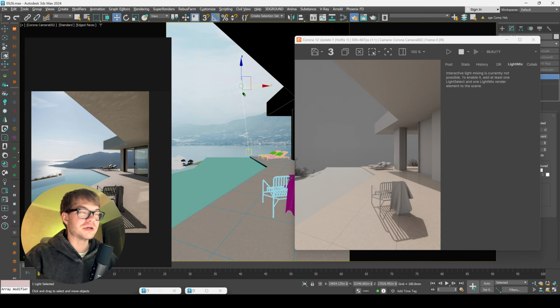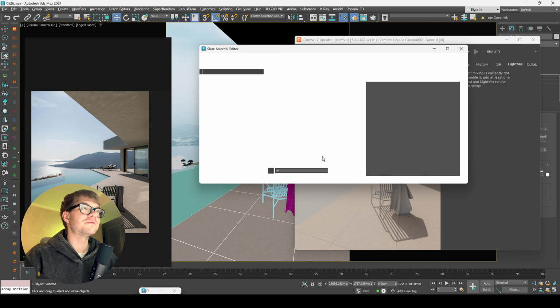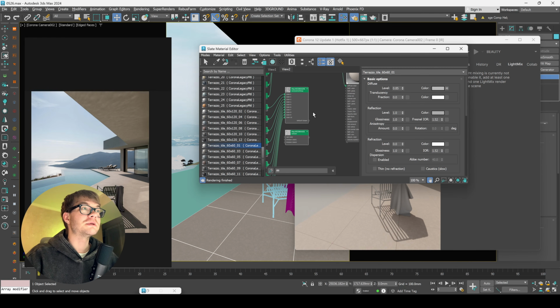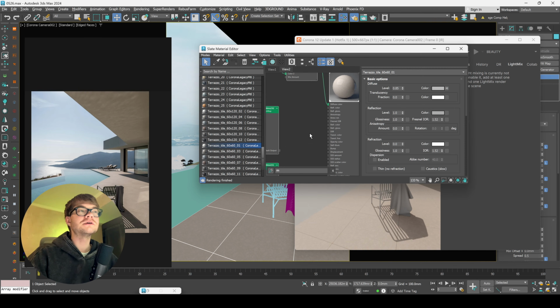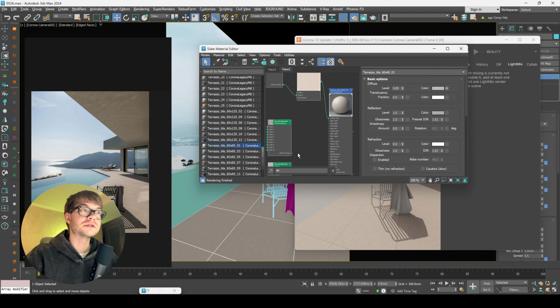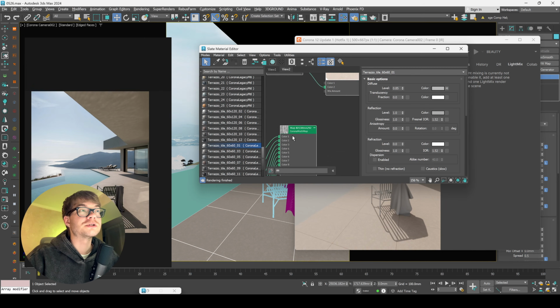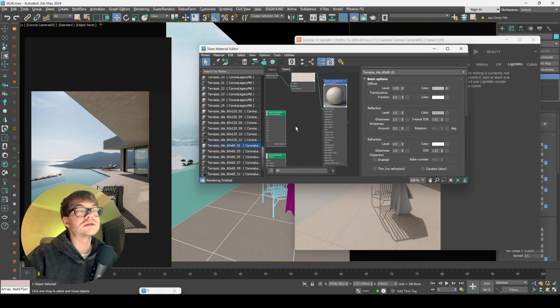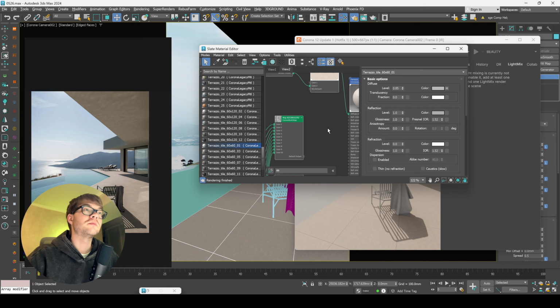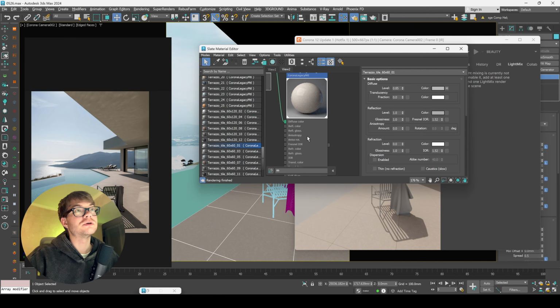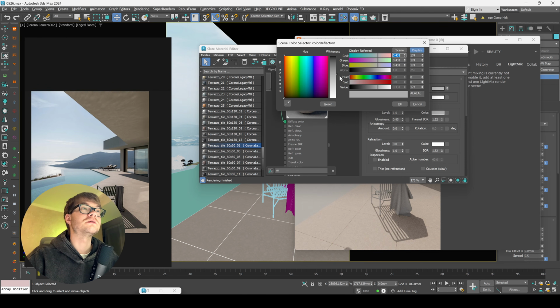Once I turned it off, it appears to work pretty well. Sometimes in the scene it will not work correctly because there are different scenarios. Maybe for interiors these reflection maps work great, but for exteriors it's too bright and there will not be so much reflection, so I can simply turn it off. And here in the glossiness, I think an amount of 0.95 would be enough. And maybe we can also increase our reflection amount a little bit this way.